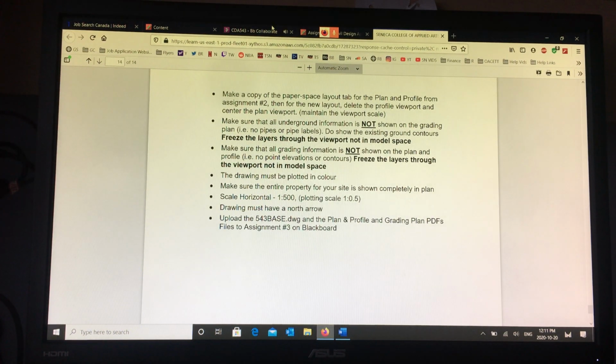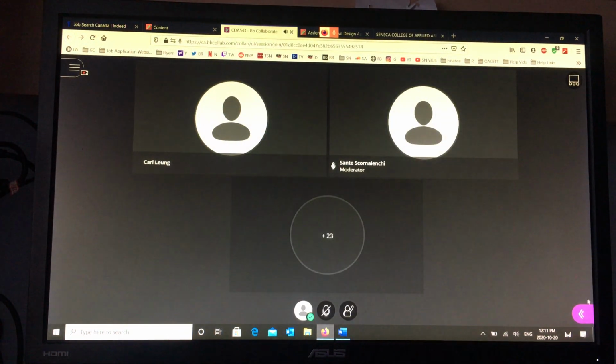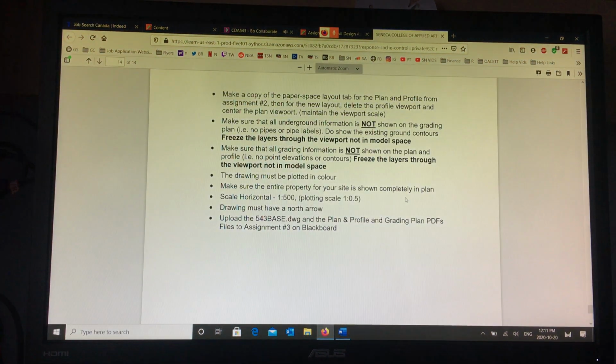Oh, in the paper space, the setup for paper space model, yeah, that's easy. I can show you. That I can explain. Okay, so when I check your drawing, I open your drawing. First thing I do is I list both of these frames. This should be 2xp, right? Or if you look at one at a time, it should be 1 to 500.